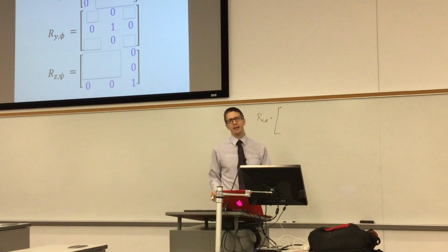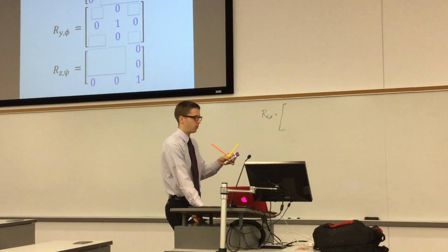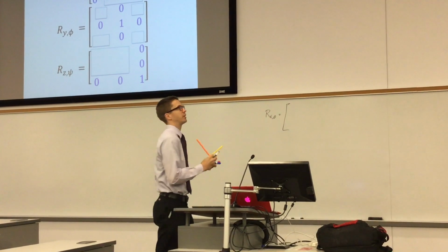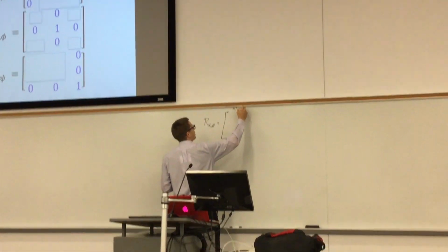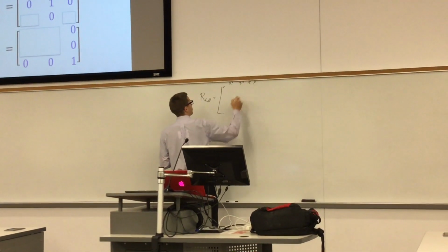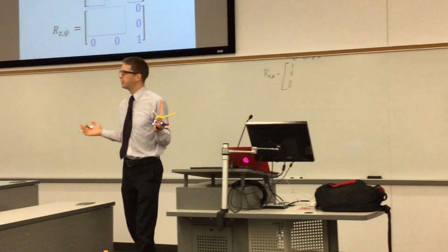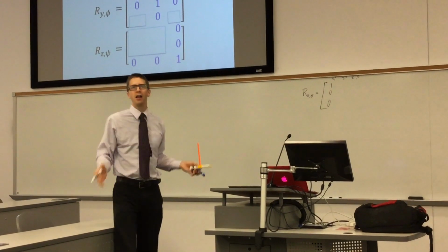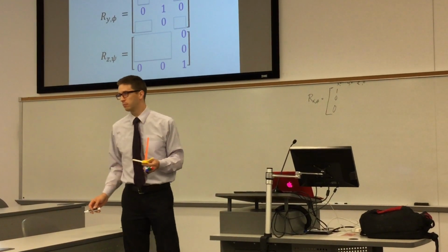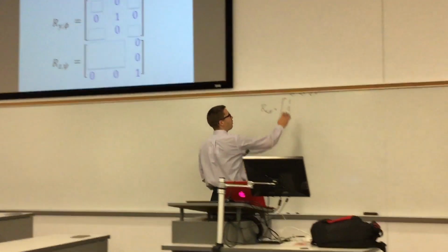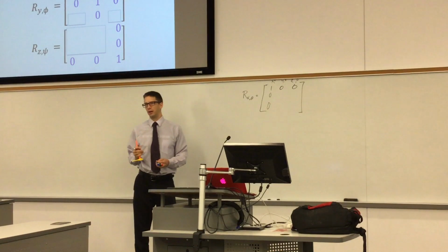I've given you these little hints: if you're rotating around an axis, then you're not going to change that axis. So you see x is always pointed in the same direction, so we get 1 for free. Remember, this is x: 1, 0, 0; y: 1, 0, 0; z: 1, 0, 0. You've got 1, 0, 0. Then we've got a bunch of basic properties of rotation matrices. The first is that all the columns are unit length, and all the rows are unit length. So we take the norm of these, which means that this row also has to be zeros. And that simplifies our life.